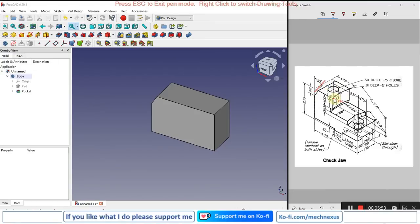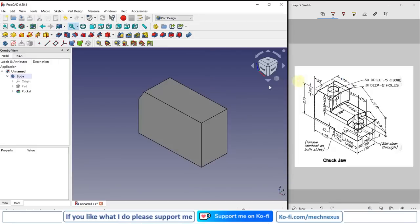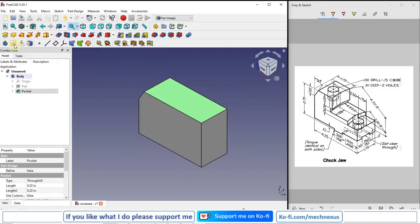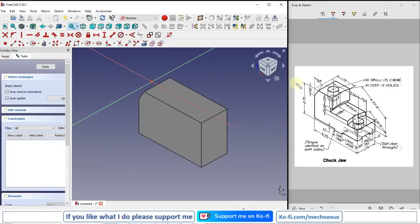Now we will make this arc cut. So we will read its dimension. Now I will select this face and I will say sketch, and I will switch to the isometric. Now for this arc we have to project these two corner edges. So first I will project these two corner edges and simply draw a three-point arc.